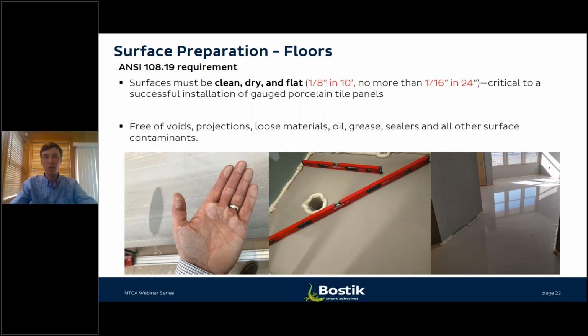These tolerances are essentially the same as large format tiles, and much of this information carries across essentially all flooring types, whether it's a resilient floor, a click-together floor, or hardwood. Decorative wear layers need about the same type of requirements. So there are a lot of requirements for surface preparation, and I've overviewed the surface prep for gauged porcelain tile, but they're very comparable to the best practices in each of the other categories. So this can apply to virtually all types of flooring applications.